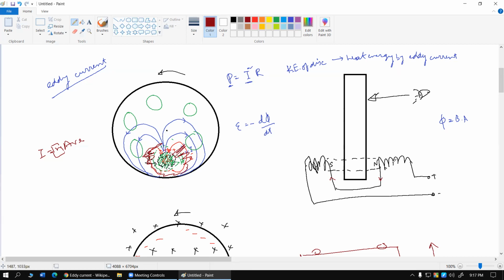By definition, this is not eddy current. If you wonder where this current is coming from, it can be produced by an alternator from the car's motion, from the car's engine, or it can be directly fed from the battery of the car. Either way is possible. But this is a current that is not eddy current. Eddy current will be totally confined within the metal disc altogether. The eddy current will not leave from here. And the basic outcome of eddy current is that.